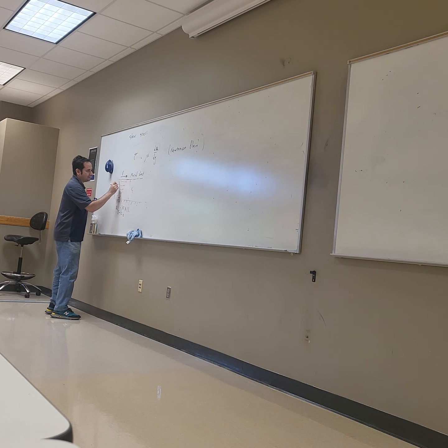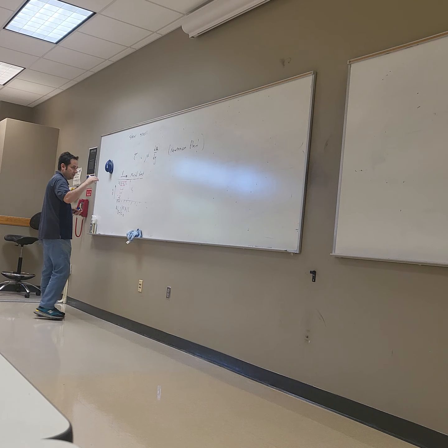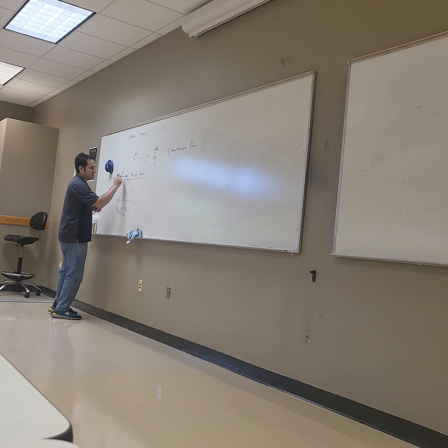What about u at y equals delta? It's equal to the velocity of the metal sheet. Exactly. Why? Because the tiny molecules of that fluid will stick. If you go to infinite molecular-level zooming with a microscope, you see that they are just stuck on this surface. So the velocity at y equals delta is equal to capital V.